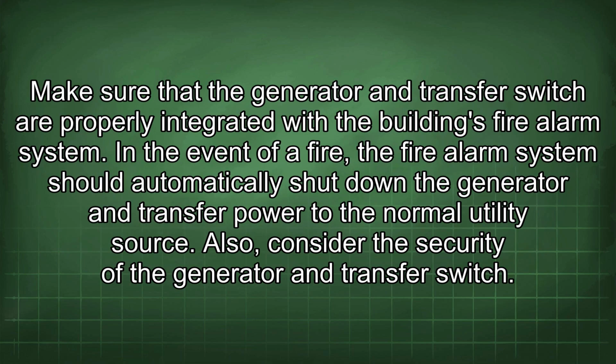Make sure that the generator and transfer switch are properly integrated with the building's fire alarm system. In the event of a fire, the fire alarm system should automatically shut down the generator and transfer power to the normal utility source. Also, consider the security of the generator and transfer switch.